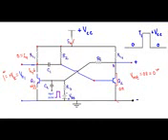It means that if I keep the circuit intact and do not apply any external triggering pulse, the output voltage of the multivibrator, that means I have taken the output across this terminal and this terminal, will stay at this 0 volt forever if I supply this VCC in this circuit. That's why this 0 is called the absolute stable state for this circuit.